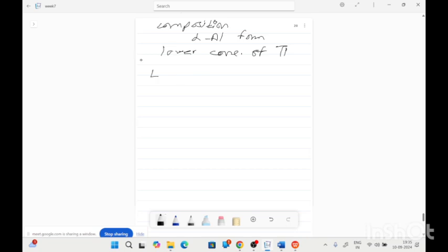So the addition of boron leads to the reaction of liquid giving alpha aluminum plus aluminium titanium boride plus the Al3Ti intermetallic precipitate.